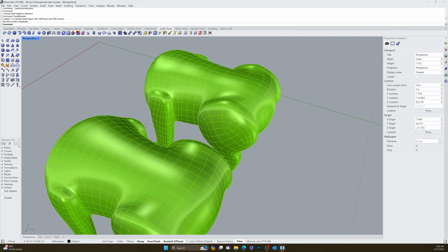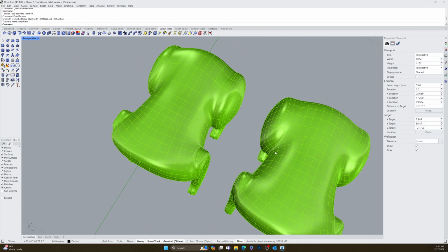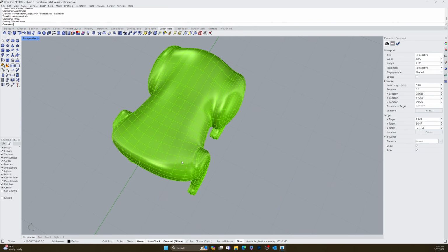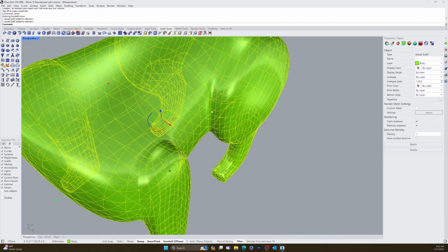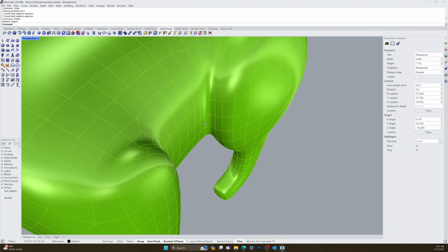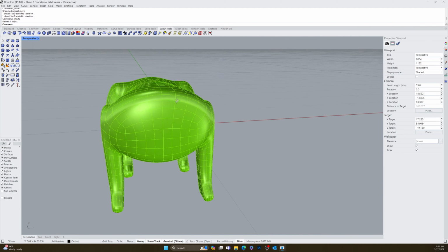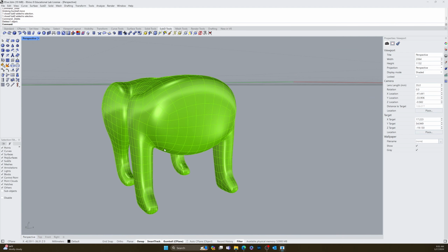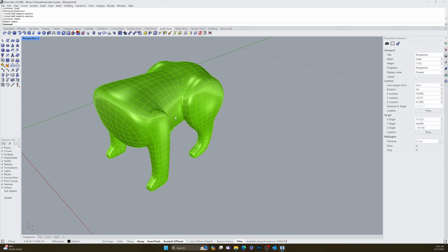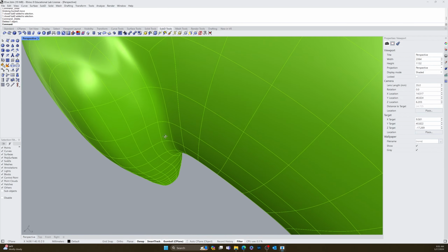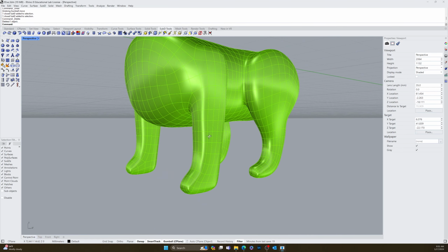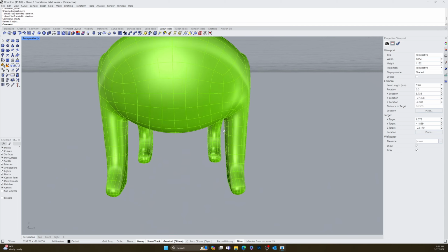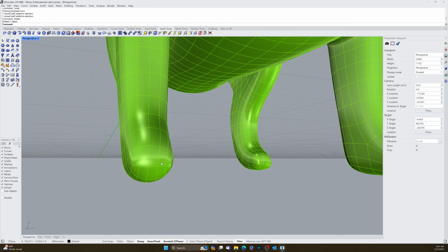And there we go. Now we've got the perfect form. So this one with the weird sections there no longer exists. So we undo that. Which one was it? Okay, I got two meshes on top of each other. That I think is the wrong one. Yeah, there we go. So now this one's all quadrangulated properly. So this one's ready to go to Pixar. You know what I mean? Like that's what I'm talking about. You want to have perfect quads all the way around it. This is like if you were going to bring something to an animation studio and be like, is this correct? They would want to see that it's quads.